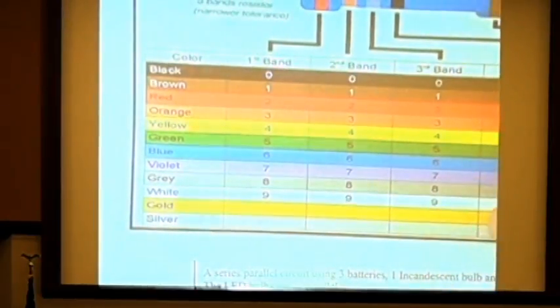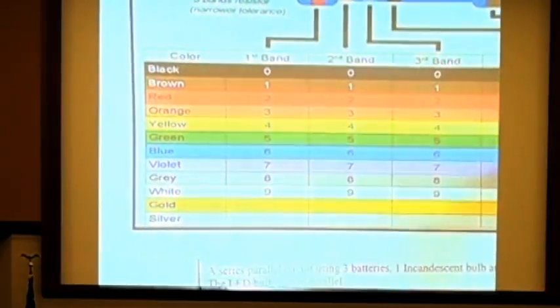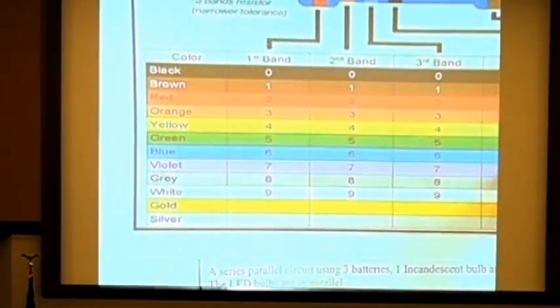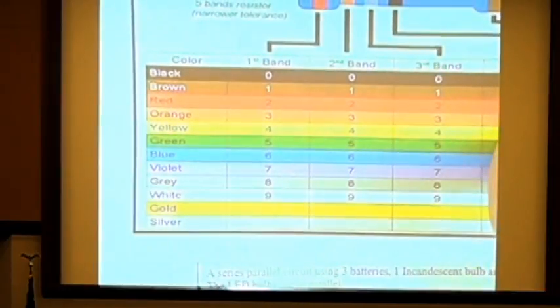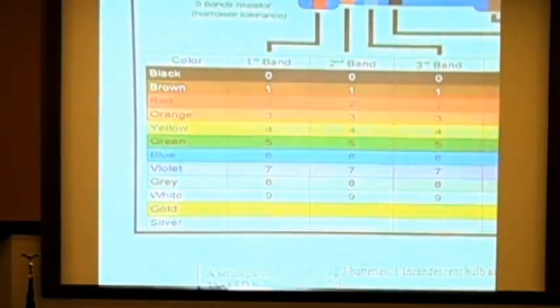The answer is right here on this one, so you can kind of figure it out, work backwards if you want. I don't typically ask 560K. I could ask that, or I could ask the zeros. I don't know what's easier for you guys to understand. If I go 2, 2, and this one, that would be 22 kilo ohms. I could do that, but I think the zeros are a little bit easier.